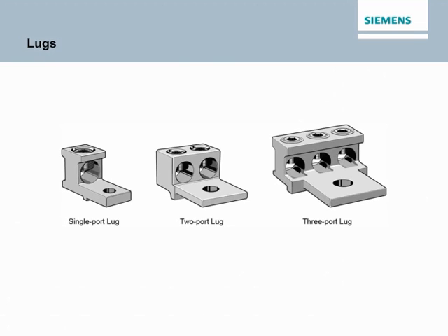The lugs connect the wires to the meter socket. Lugs may be factory or field installed and are available with single or multiple ports. Multiple port lugs allow for the use of multiple wires. Lay-in lugs are also available. Lay-in lugs are fixed and may not be changed in the field to accept other wire sizes or parallel conductors.